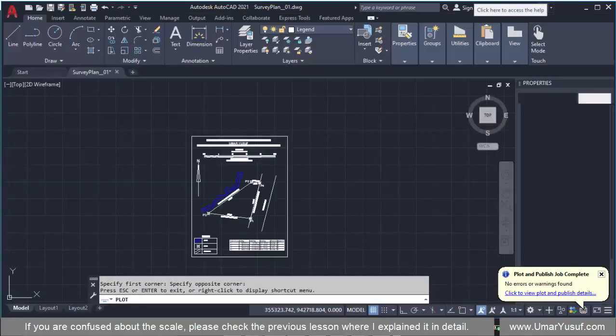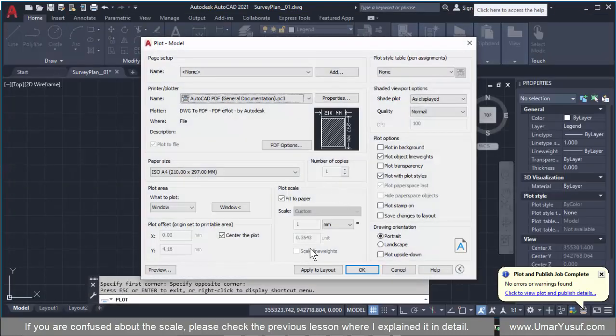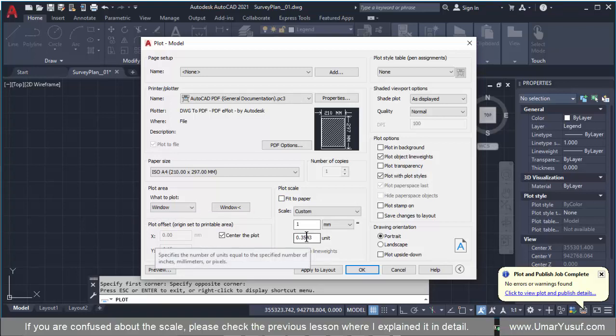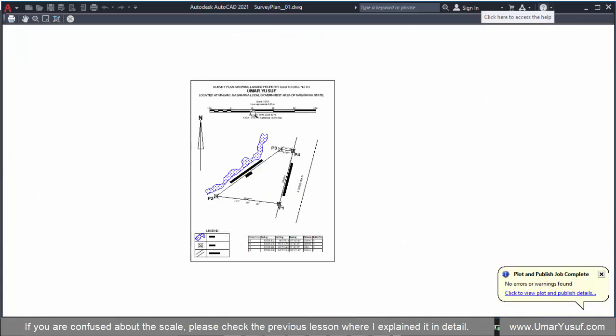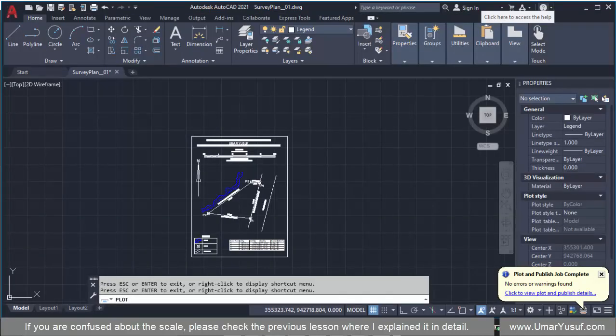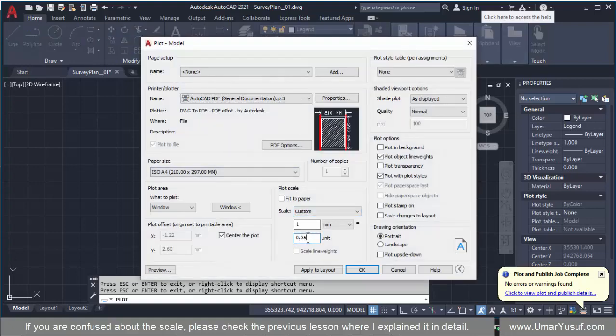And if I go back, exit, go back and check the scale that fits in, you see that the scale that fits in is 1:300, 350, 354 approximately. So I can change it to 1:350. Let's see how it will fit in. So you can see 1:350 also fits in. But 1:350 may not be a conventional scale for a land surveyor. So we may need to change it to maybe either 1:300 or maybe 1:500.